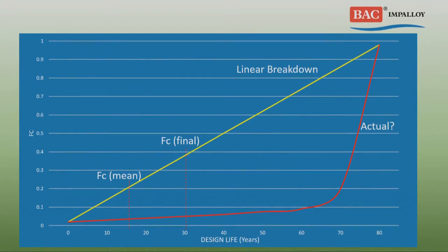And that is calculated from the mean coating breakdown. So the mean coating breakdown there will be something like 5 times the amount of current that we actually need. And the anode mass is directly related to the current.